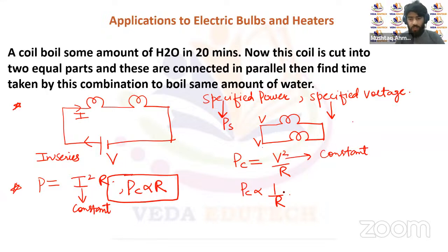So if we want to maximize the output of the bulb with higher resistance, put that bulb in a series combination rather than parallel combination. If you put that bulb in a parallel combination, it's going to glow less as compared to the bulb of lower resistance.